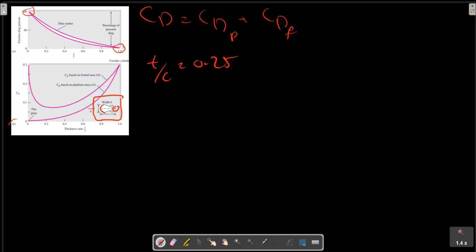Note that the drag force coefficient in picture B, shown here, looks quite different when based on the frontal area instead of planform area. Planform is the usual choice for this body shape. The two curves in this picture represent exactly the same drag forces.